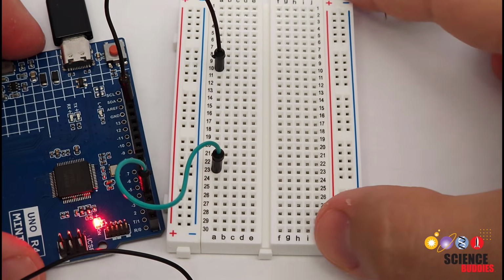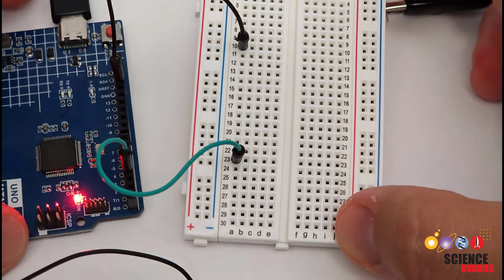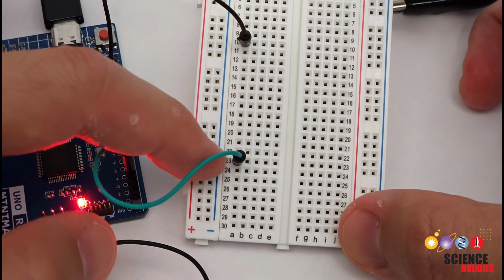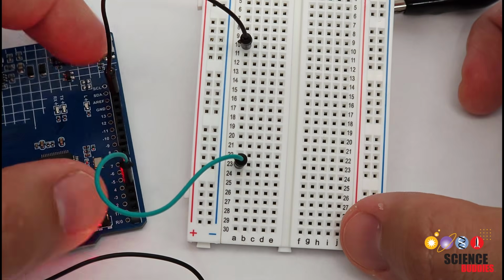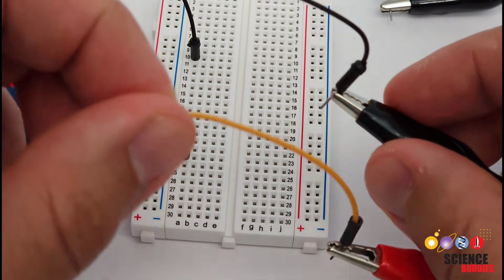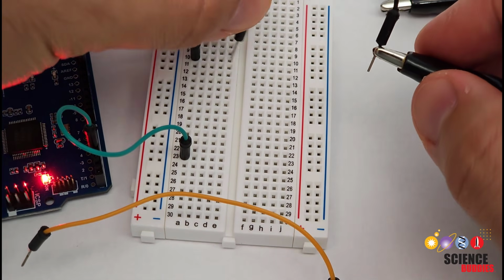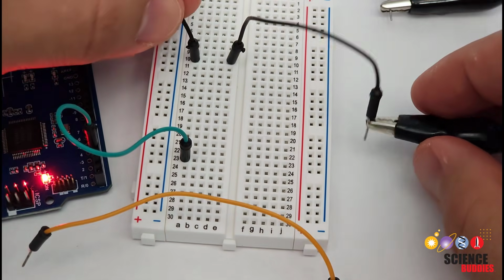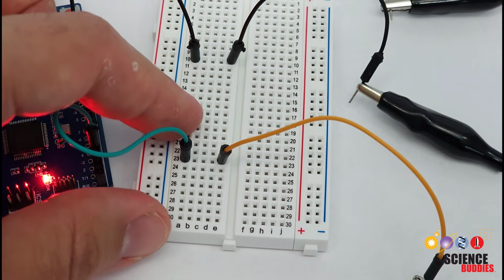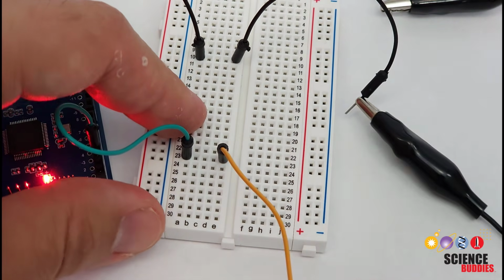First, let's see what happens if I just connect my two transmitters directly to the Arduino pin that's generating the signal. So I'm going to take one jumper wire, go from my Arduino pin 3 to a row on my breadboard, and then take another jumper wire and go from the Arduino's ground pin to a row on my breadboard. I'm then going to connect alligator clips to jumper wires, plug one into the same row as that ground jumper wire, one into the same row as the jumper wire for pin 3, and then the other ends of the alligator clips are going to go to the two pins on my transmitter.